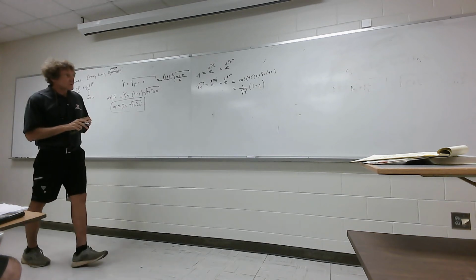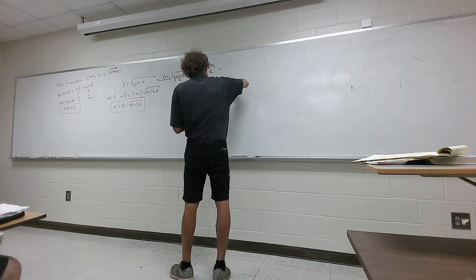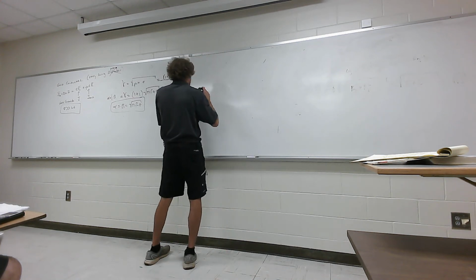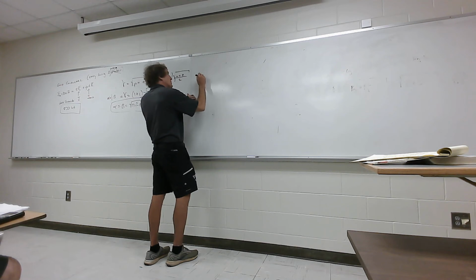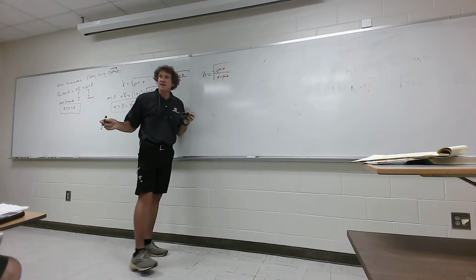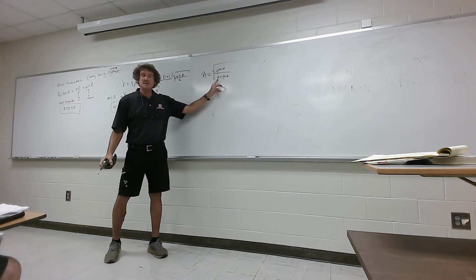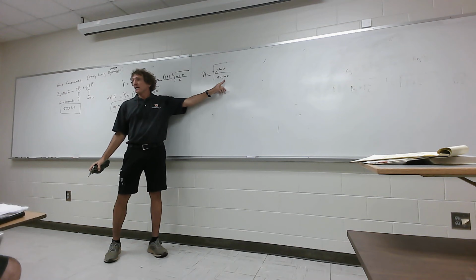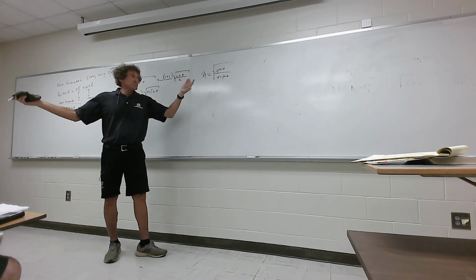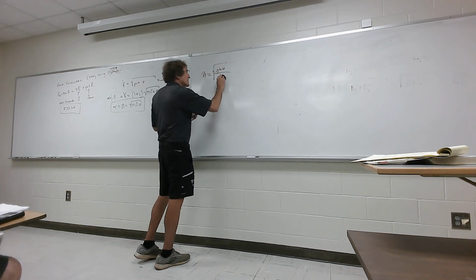So next we go to the intrinsic impedance. Let me just get this out of the way. That's equal to square root of J omega mu over sigma plus J omega epsilon, right? Now, when it's a good conductor, what happens here? Somebody help me out here. Ignore omega epsilon, right? Because sigma is so much greater. You all follow me? It's added. Now, what does that become?